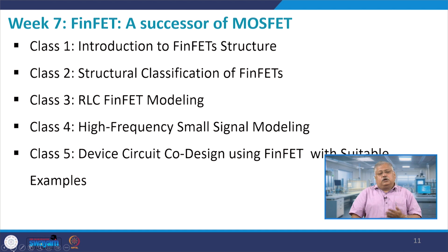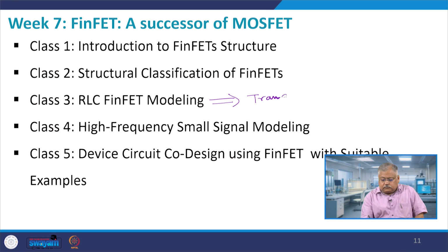This is important because you need to extract the FinFET's capacitance, parasitic capacitances, parasitic resistances and inductances, so that you can predict its frequency of operation when you are doing an AC frequency or even a transient analysis. For DC analysis, of course, they do not make any sense, but for transient analysis they are very important, and therefore this FinFET modeling will be used more so in transient and AC analysis, right.